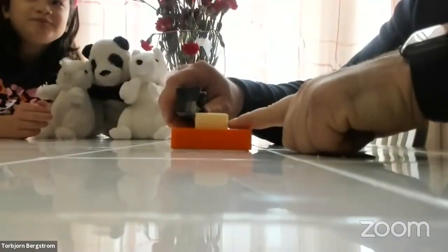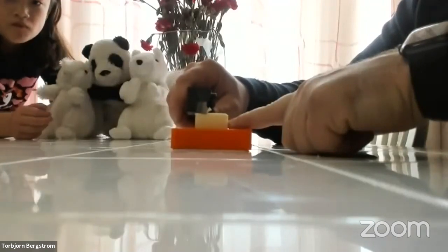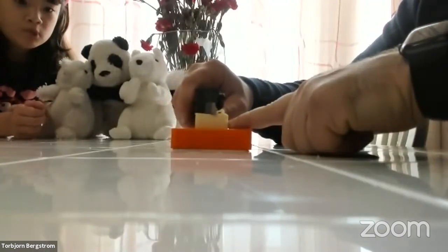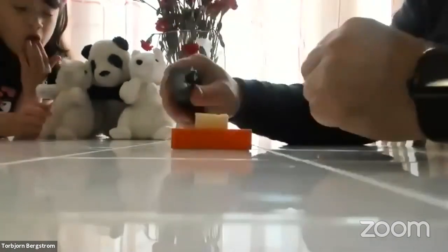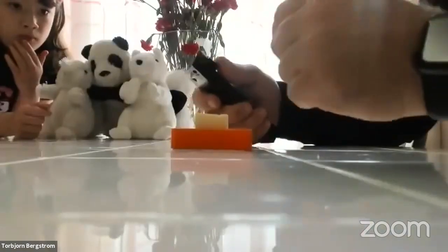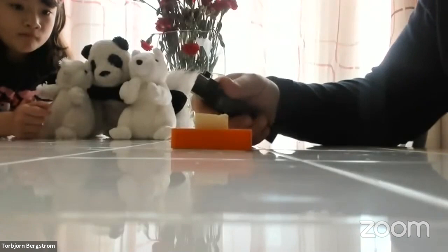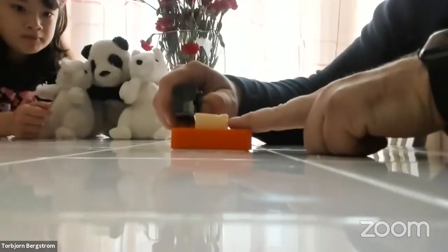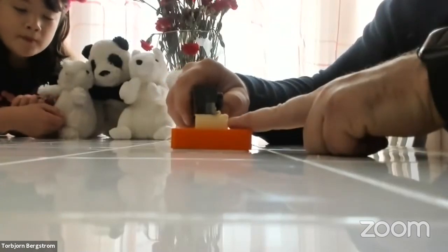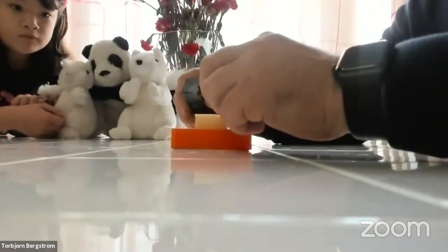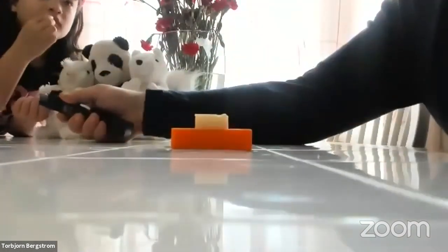Now, I'll do it again. You will slowly make a chip across the top of the workpiece. And so at that time I had a little bit more down pressure. My uncut chip thickness was changing over time there, I think. We'll try one more time here. You make the chip across the top of the workpiece. Once more. Be careful, the cutting tool's sharp.